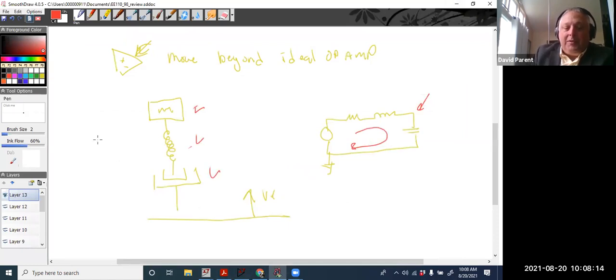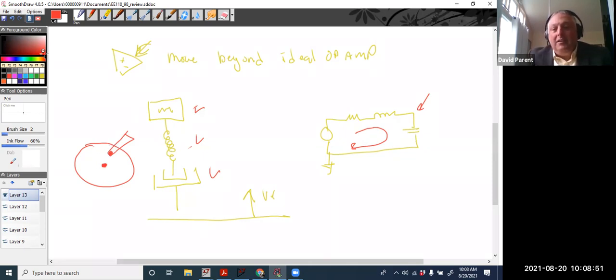a hard drive controller where you have a disk, right? And you have the head, this is spinning, right? This has to move back and forth to read the data. That movement is a physical system that has a mass. That arm has a mass, it has a spring coefficient, it has a damper system, right? And so you could simulate, verify, and design things in LTspice on just the movement of where the head will be.